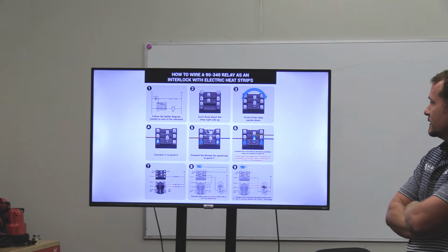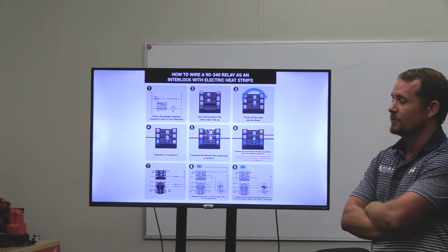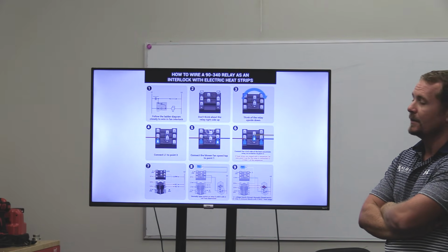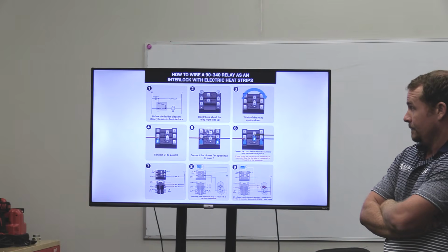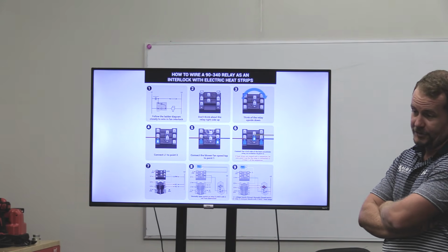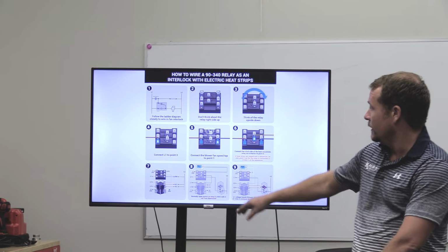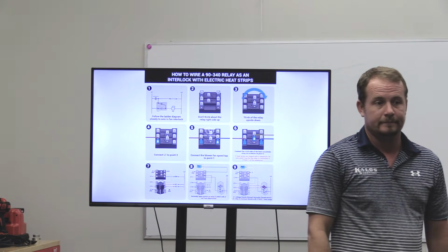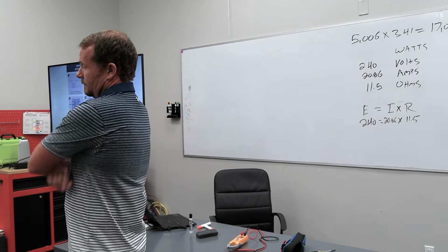So 2 will only ever be energized if the heat strips are already calling, correct? Correct. Yeah, terminal 2 cannot be energized otherwise. Yeah. Because if the blower's not running, well, then there's not going to be any potential there. Right. If the blower is running, then that relay is going to be the opposite position, and this guy here is going to go open, which prevents it from backfeeding. Make sense? That's a standard heat interlock.